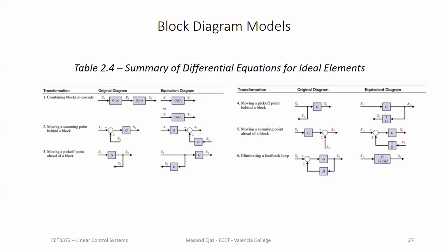So as you can see, the first one, cascading of blocks, as we just discussed: if you have blocks in series, you can always combine those blocks by multiplying them together, multiplying the transfer functions together.